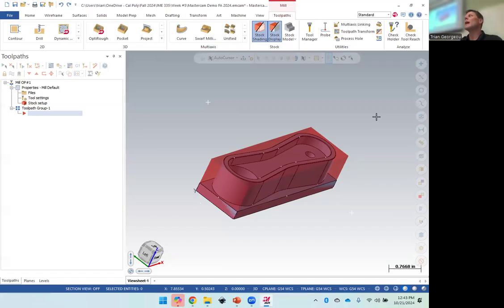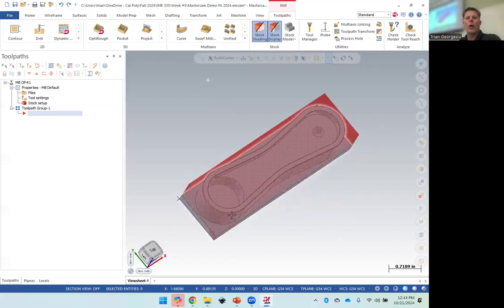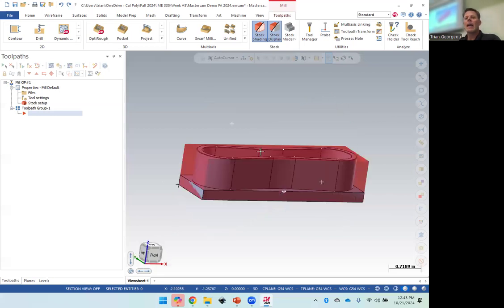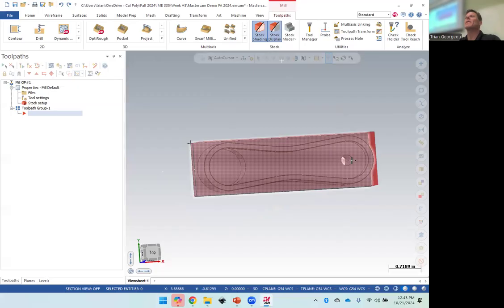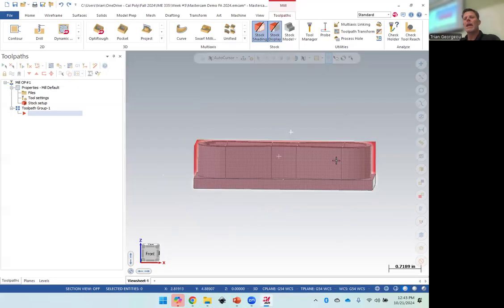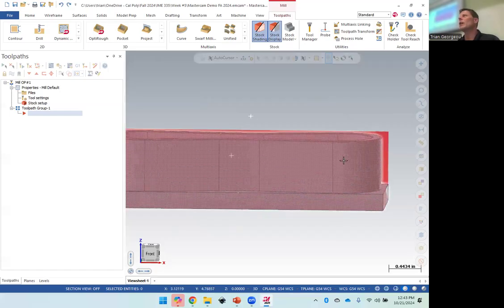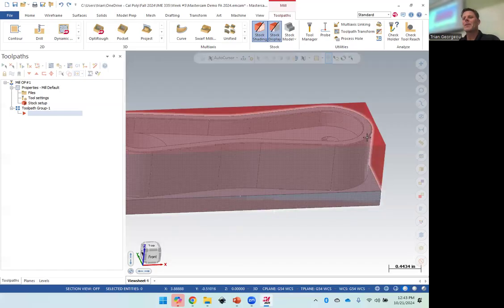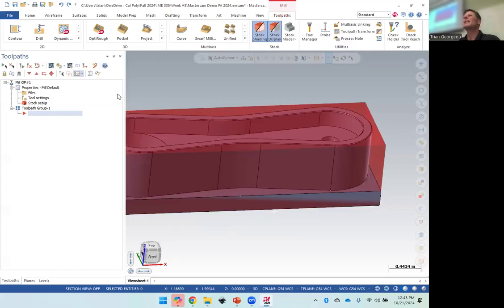Yeah, so we'll contour on the outside, we'll pocket on the inside. Then we're going to do maybe a bore to make a hole. Sound good? And then when we have a hole that's small enough for a drill, what do we use? A drill bit. We're going to drill. And so we don't cut ourselves on this widget, what should we do last? Chamfer. So that's basically what we're going to do.